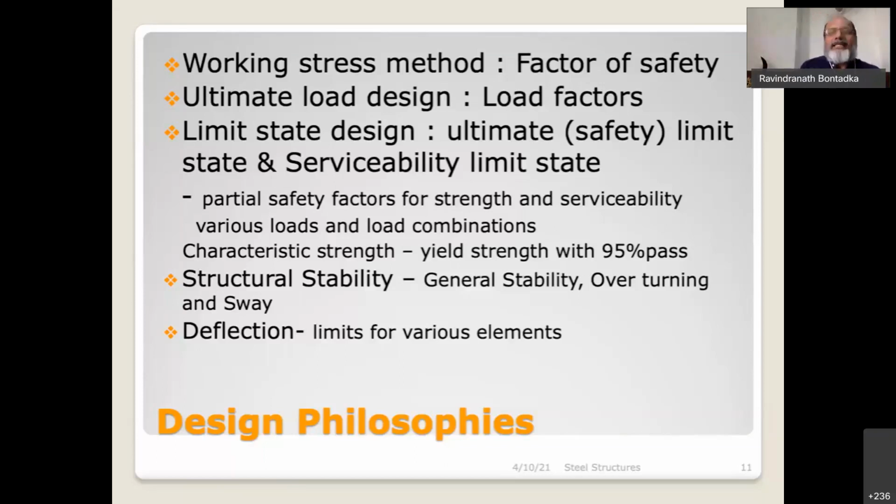One is the ultimate limit state on safety and the other is the limit state on serviceability. The limit state on safety considers the load factor on the total load and whether the member is safe to take the load, whether in tension, compression, bending, and all these factors.